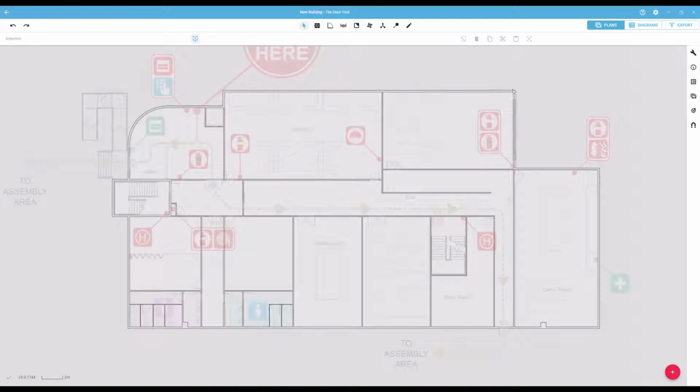Before you can start placing doors on a floor plan, Plan Studio requires you to first have all the walls already drawn. We then add doors into the walls, and the doors will create their own opening into the wall. Selecting our Opening tool and using the Doors option in the sub-toolbar, you will then see all the different door types available on the right-hand side.